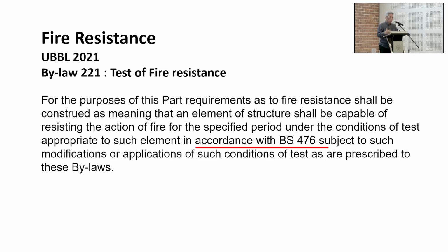If you're talking about the wall element, you go to part 22. If you're talking about flame resistance, the surface spread of flames, to achieve class O, you have to go for part 6 and part 7, etc. So there are all these tests related to BS 476.